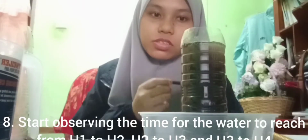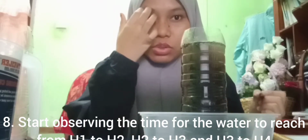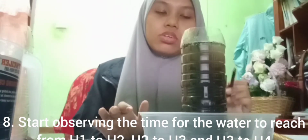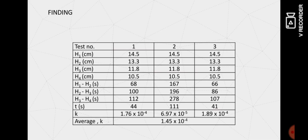Then start observing the time for the water to reach from H1 to H2, H2 to H3, and H3 to H4. After it finishes, you have to do it with the different types of soil. For the finding of the permeability test, the average coefficient of permeability I got is 1.45 times 10 power of -4.